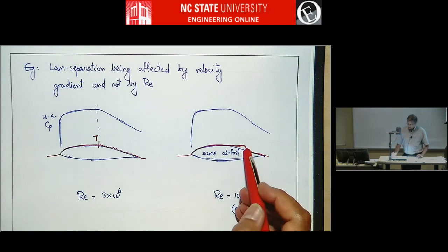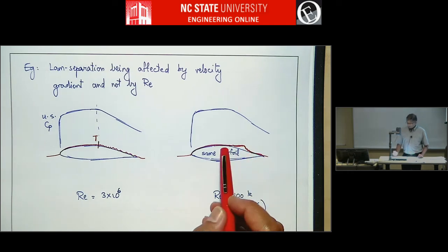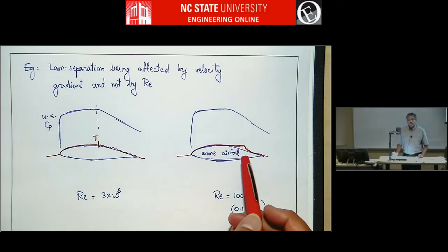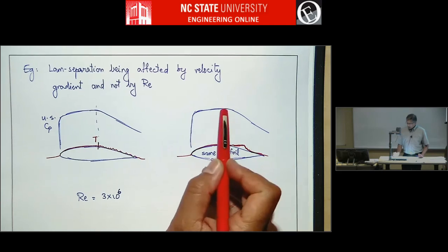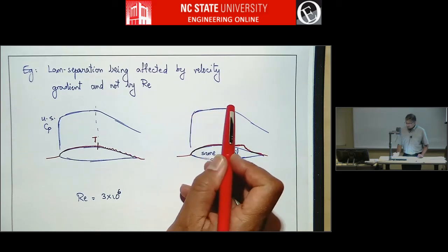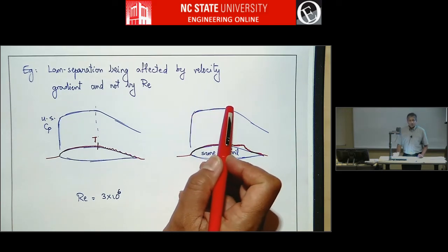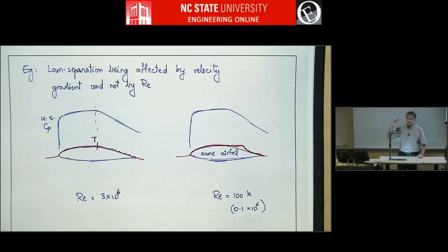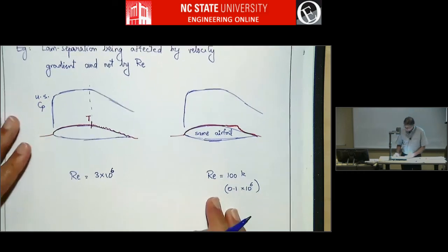So if you want to avoid this bubble, you can reshape this airfoil and avoid having so much favorable gradient for so much distance, right? Favorable gradient keeps it laminar, and at this Reynolds number, it automatically wants to stay laminar, so why bother with favorable gradient? So if I'll draw the third airfoil here.